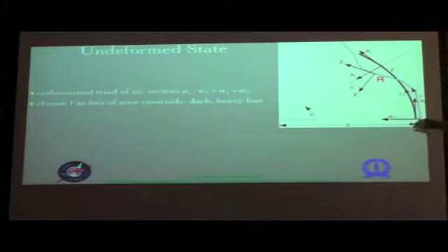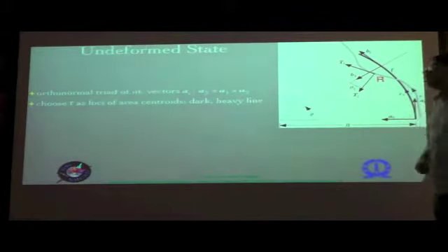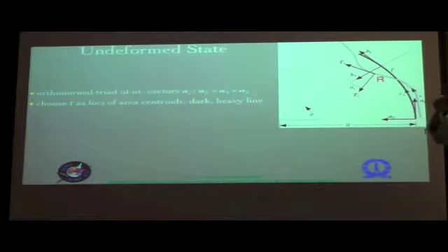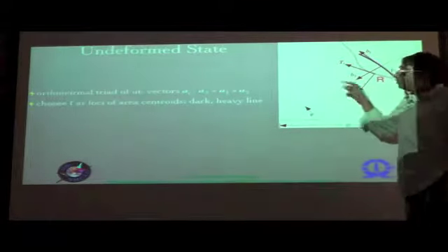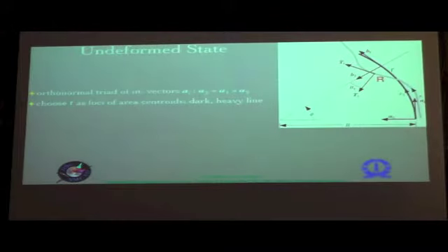Now we choose R. Again, you have a choice for R. How do you define the reference curve? We have been stating that we have freedom in terms of what in the cross section we can choose as the reference curve. Let us say in this case we choose it as the loci of the area centroids. We have to distinguish between mass centroids and area centroids, especially when we get into the dynamics in the last class. We'll do that. But right now, as far as the choice of R is concerned, it's the loci of the area centroids, and that's the dark line that you see in the picture.